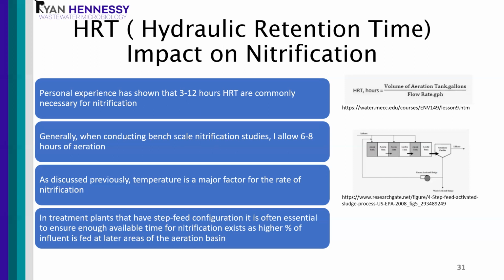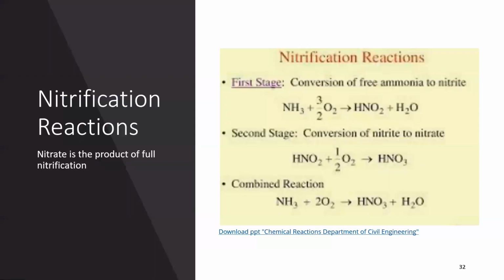When organic acids are oxidized by our heterotrophic bacteria in wastewater, generally within that first 15 to 30 minutes of the aeration basin, we're going to get a lot of oxidation. We're going to get a lot of storage, and the majority of the BOD that's readily available tends to be either oxidized or stored really quickly in the reactor, where nitrification is going to take much longer.